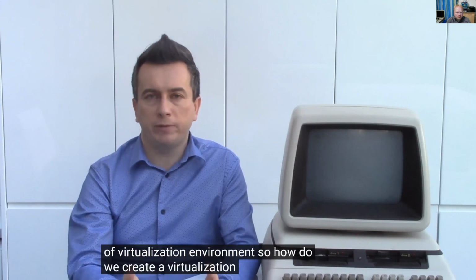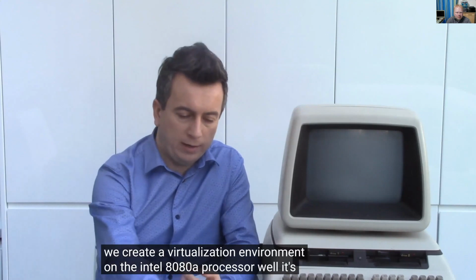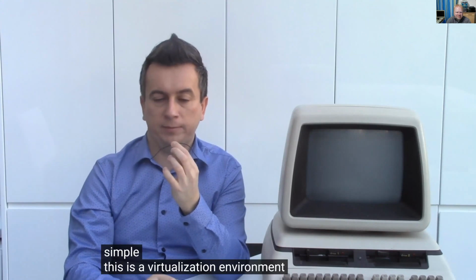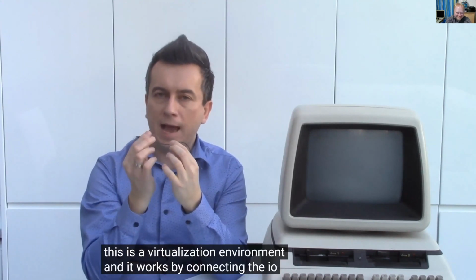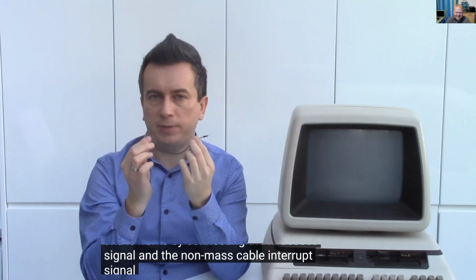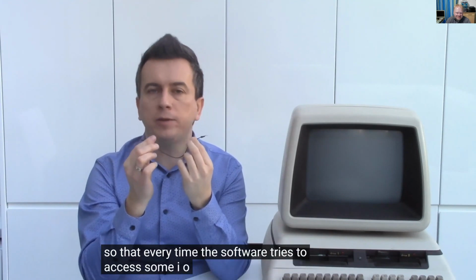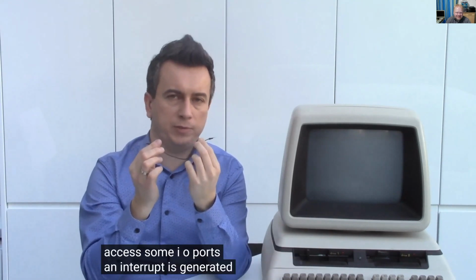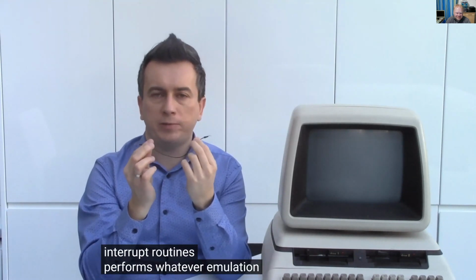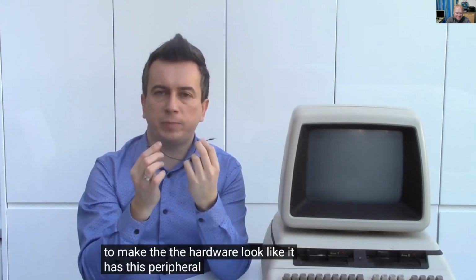So how do we create a virtualization environment on an Intel 8088 processor? Well, it's simple. This is a virtualization environment. It works by connecting the I/O access signal and the non-maskable interrupt signal, so that every time the software tries to access some I/O ports, an interrupt is generated, and the interrupt routine performs whatever emulation is necessary to make the hardware look like it has this peripheral.